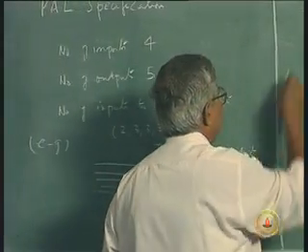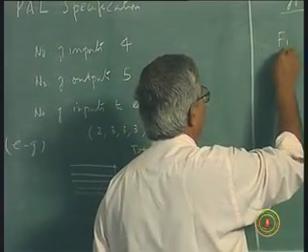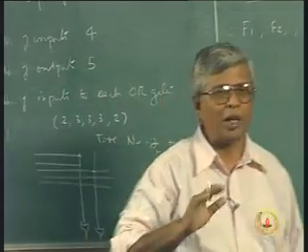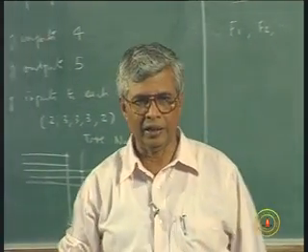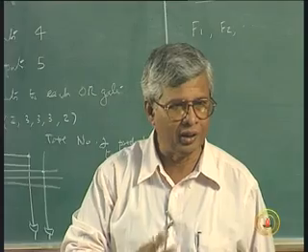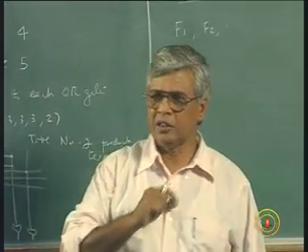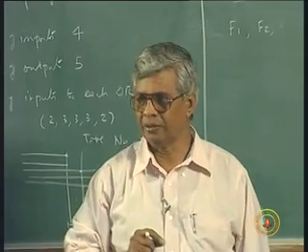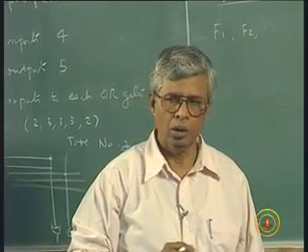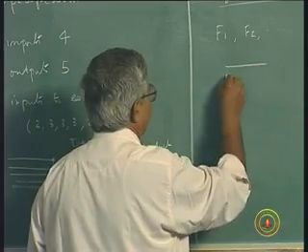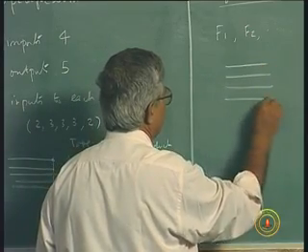See, each of these functions F1, F2, etc. We normally, as I said, till now it is only combinational logic. I have been saying combinational logic design using programmable logic devices. Is that right? So, we will have an output function in terms of P0, P1, P2, P3, etc. Now, simply like this, each of these is an AND gate.